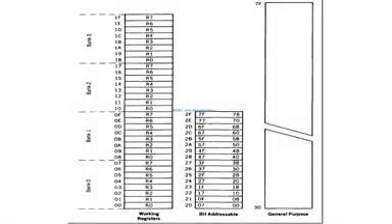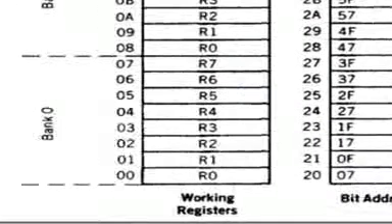So see this, if you take register R2 of bank 0, that is at which location? 02 location. So I can use this location in two ways, either by its name or else by its address. If I use it by its name, I can say R2. Okay, if I use it by its address, I can say 02H. So I can use this location by using its name or else its address. Is that fine?